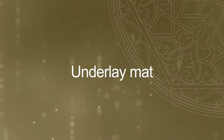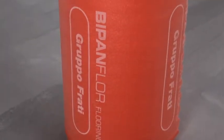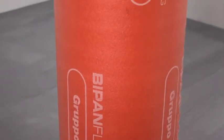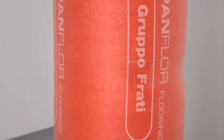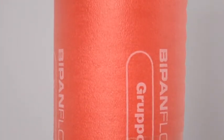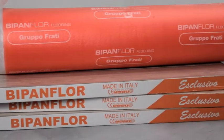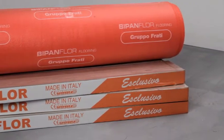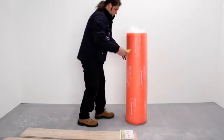Underlay mat. In order to level slight differences in height of the underlying floor, it is advisable to use a 2 mm thick expanded polyethylene sheet, which also helps reducing sound. Polyethylene sheet. Use ring-laid polyethylene sheets or an HD polyethylene sheet strictly 2 mm thick.